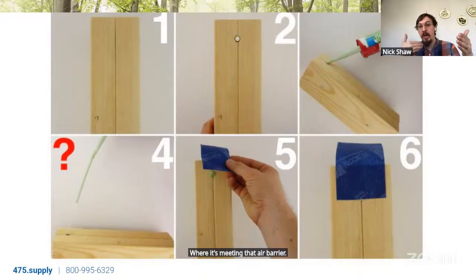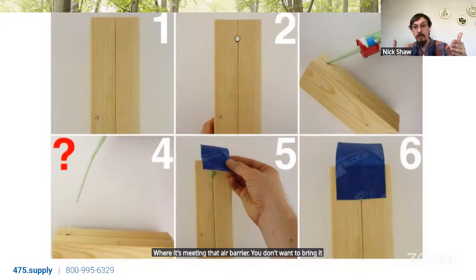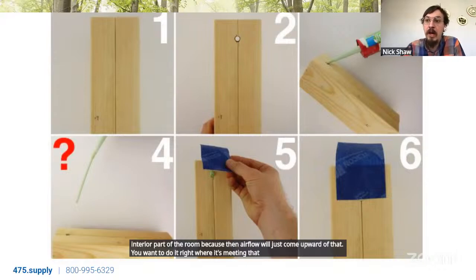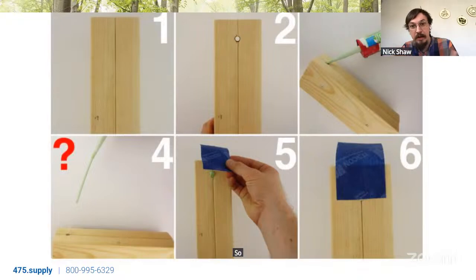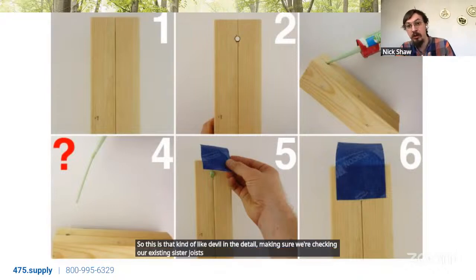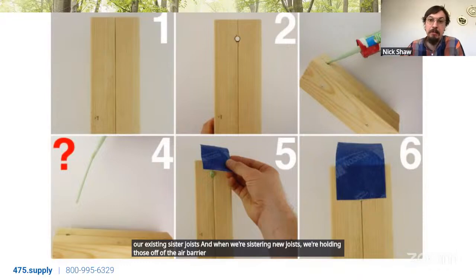You don't want to bring it out into the interior part of the room because then airflow will just come upward of that. You want to do it right where it's meeting that air control layer. So this is that kind of like devil in the detail, making sure we're checking our existing sister joists. And when we're sistering new joists, we're holding those off of the air barrier so we can tape around that existing beam.